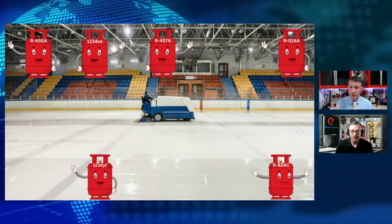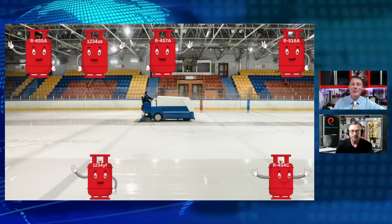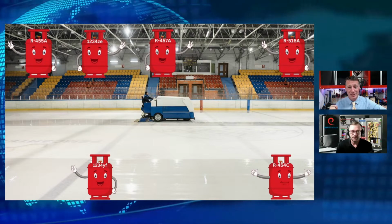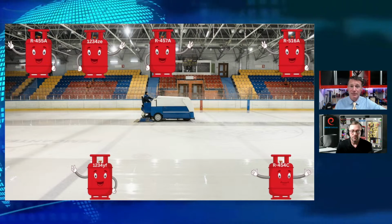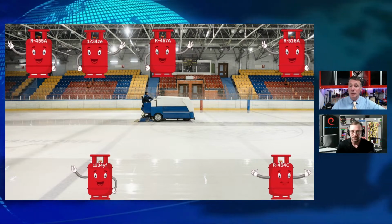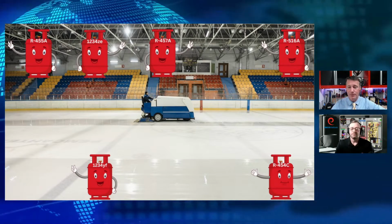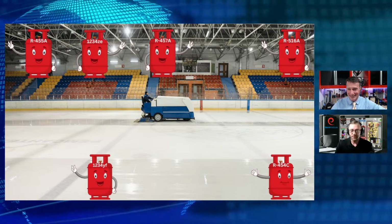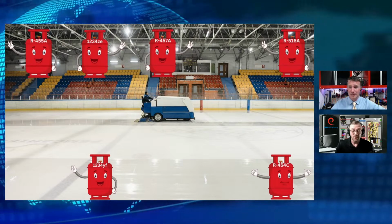So our most common replacements that we're going to see now going into new equipment for these are going to be our 1234YF, our 1234ZE, and we also still see some of that 454C, 455A, 457A, and the 516. So still a little variety depending on what the manufacturer is going to design their system for and, I'm sure, the cost of refrigerant at the time of manufacturing. It's going to be a big deciding factor for these manufacturers. Availability as well, right? Yeah.